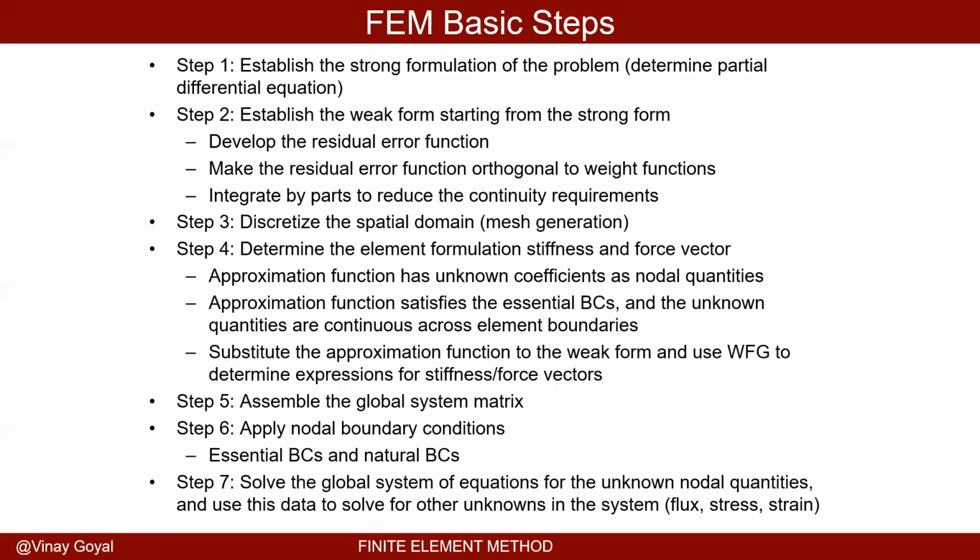And that allows me in step number 5 to then assemble back all the elements together and apply the nodal boundary conditions, particularly the essential boundary conditions and the natural boundary conditions. That enables us to solve the global system of equations for the unknown nodal quantities, and then I can use that to post-process the results to understand and solve for the flux, stress, strain, and everything else.